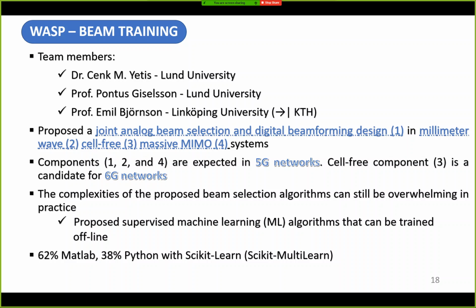So I will go through our beam training results. In this work we were 3 of us. We proposed some more advanced but still simpler beam selection algorithms, because as I mentioned, since the number of antennas is a lot in 5G networks, beam selection can be extremely complex, so we cannot propose so advanced algorithms.